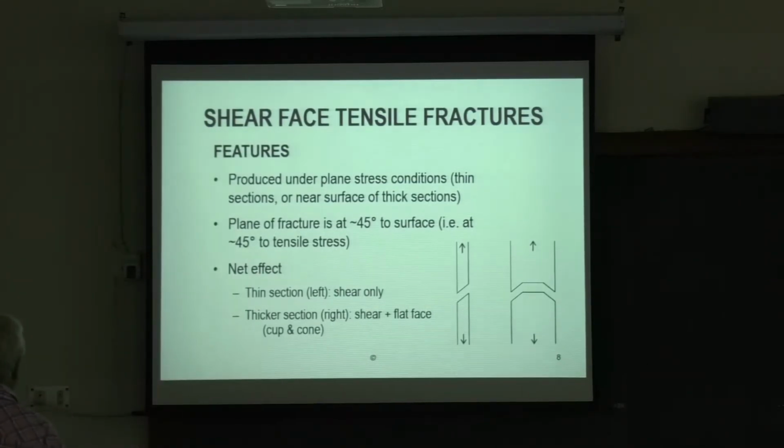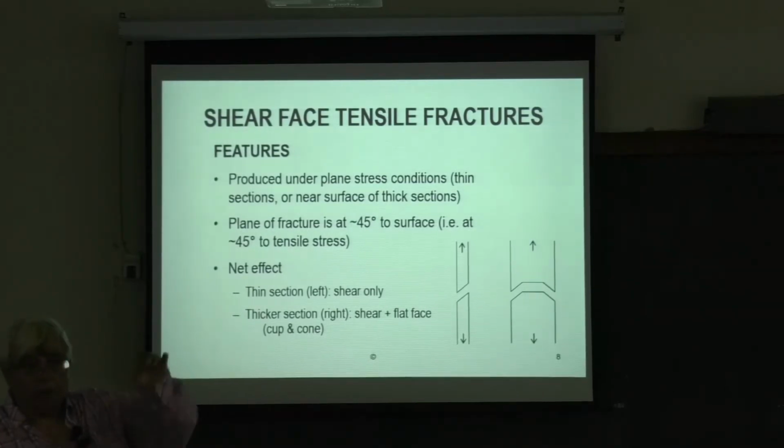But you have to know this when you do the fracture toughness, K1C. Do you remember K1C? There has to be a minimum thickness above which you have to do the testing. Yes, sir. Fracture toughness K1C, you have to have a minimum thickness, because if you do that, the stress intensity factor keeps coming down with thickness, and the lowest value of the stress intensity factor is the K1C. Okay? Yes.